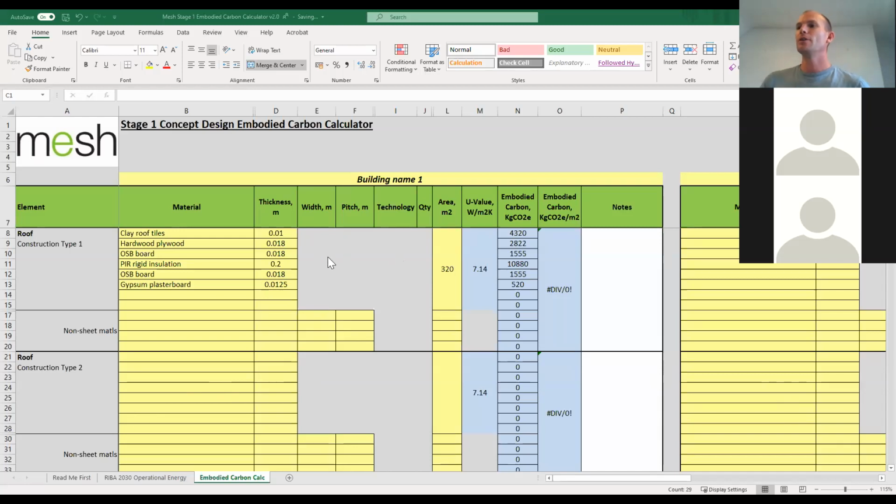Yeah. So I say apologies, I was messing around with this calculator before the talk. What we should see here, and luckily I'm not demonstrating for Apple here, is that the U value will immediately update. So as you add in these thicknesses for the materials, the U value will update. And as I say, I promise you on the one that you download, that will work. So the U value instantaneously updates, so you can get immediate feedback on what your U value is.